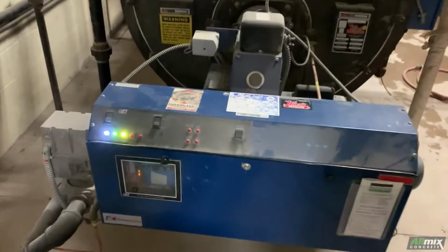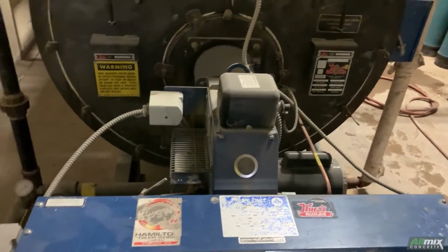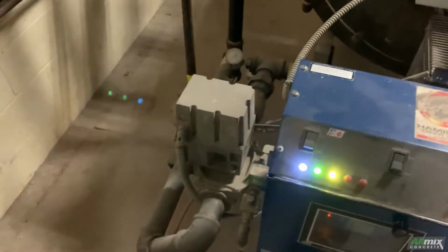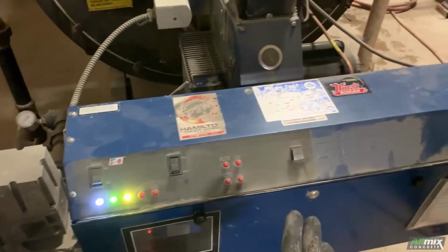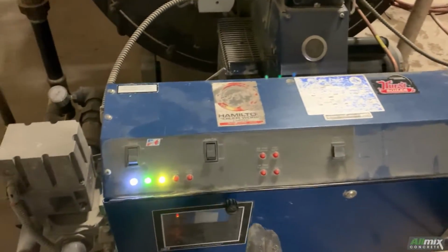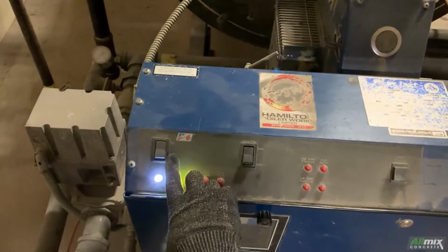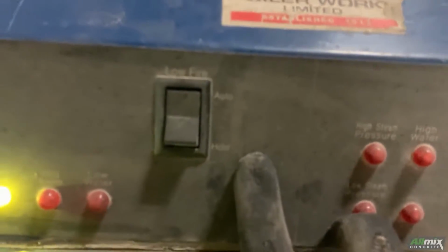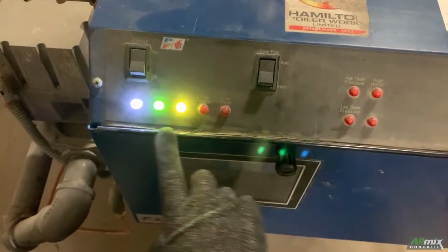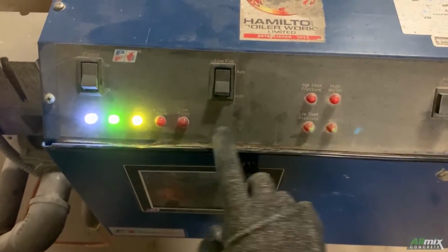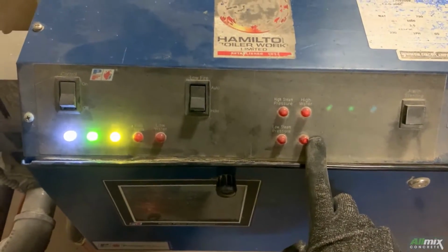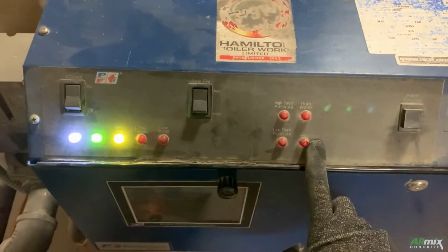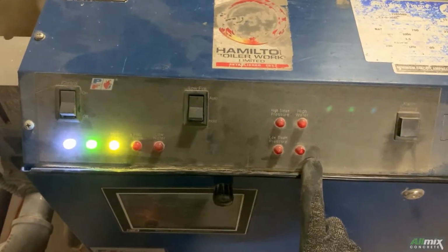The furnace is where the natural gas is ignited and the resulting hot gases are sent through the boiler tubes. This also acts as the main control panel for the boiler. Here is where we will start and stop the furnace, and hence the boiler, where we can switch the boiler into low fire mode when steam is not actively in use. It's also where we can see the current boiler activity and demand, and where we can see the cause of alarms, allowing us to troubleshoot or understand which actions need to be taken to correct the system.